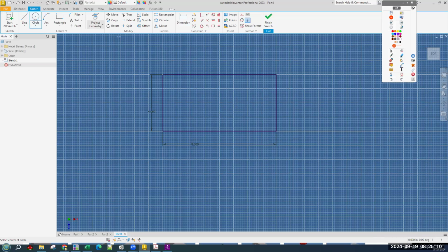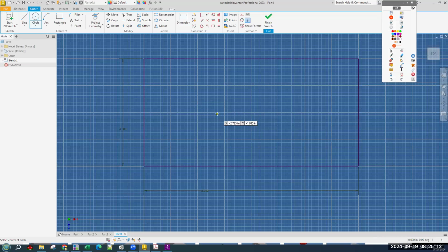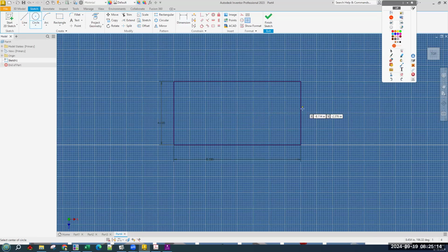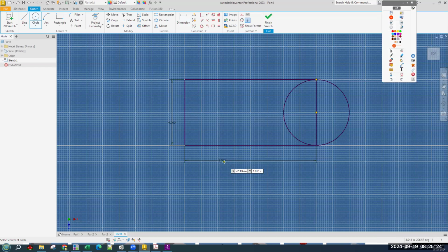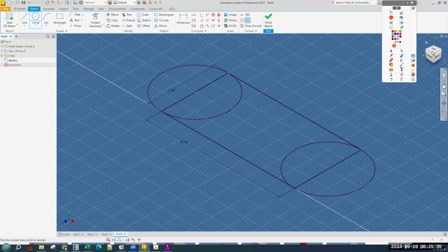And semicircles from the center point to the corner on both sides. I've got 8 wide, 4 front to back, and I'm going to start on XZ because that way we're still drawing a footprint here.